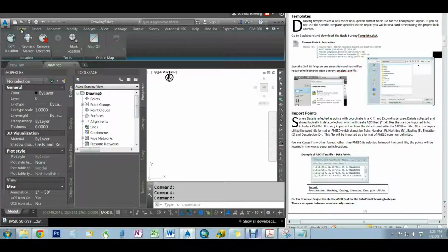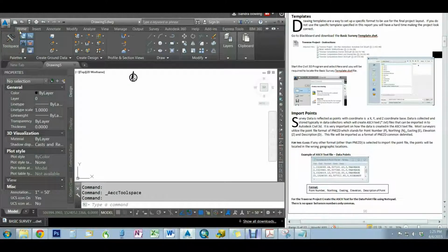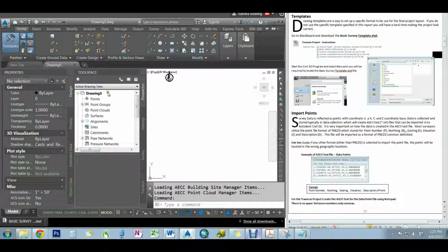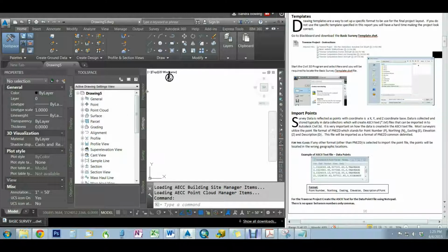Now the difference between regular AutoCAD and Civil 3D is this tool space area, the prospector. You can open and close the tool space area just by clicking on the Home tab and the palette tool space. What it has in it is this prospector, the settings, the survey, all these different tabs. The prospector is where work gets done. You're working with point data, you're creating surfaces, you're creating alignments, profiles for the highway classes or for road work. If you click on the settings tab, you'll see that they have different styles.